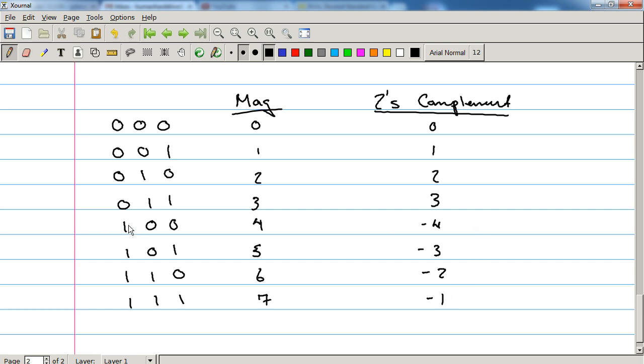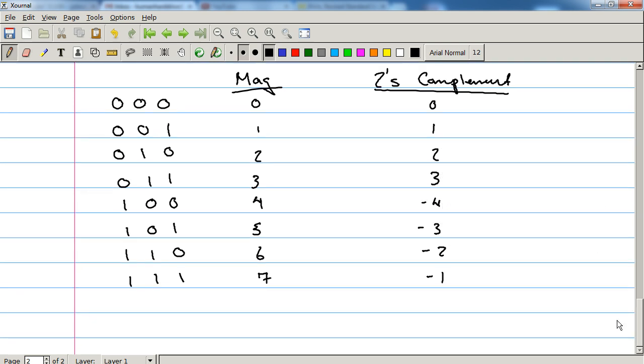So right as it gets to the most significant bit, it gets flipped, and then you start counting up. So from negative 4 to negative 1, and then from 0 to 3. Something you can probably note from this is that the magnitude goes from 0 to 2 to the n, minus 1. I feel like there's a better way to represent that. There: 0 dot dot dot 2 to the n minus 1.